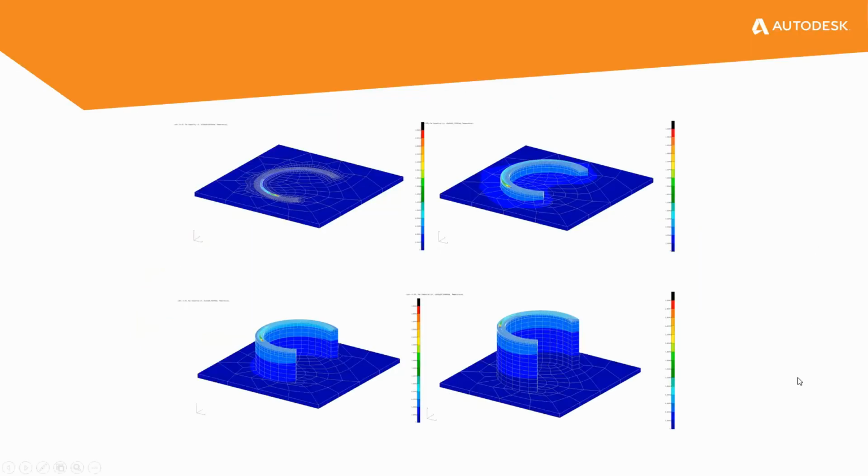What does this adaptivity look like? It means when you're solving a particular layer, that's where most of the fine elements are. But once you're done solving, it goes away, as you see in the left-hand side image. And then as you keep building on top of that, you will see that only the layer which is being solved has the fine elements. Everything below that just automatically keeps getting larger and larger. And that means you just have less data being stored, less data being solved at any given point of time of the simulation.